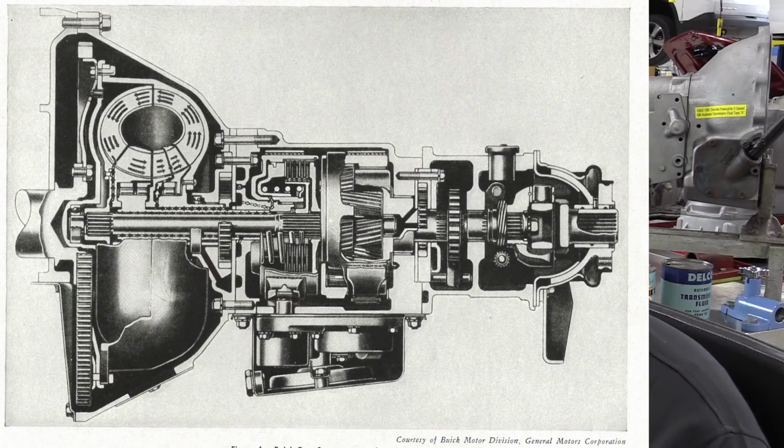It does not increase the power of the engine, but it increases the power delivered from the engine to the input shaft. Well, this torque converter has 3 stators in it and has a torque multiplication factor of almost 2.6 to 1. So you could take engine torque and multiply it by 2.6 under heavy acceleration conditions and make it feel like it had more than just 2 gears in the automatic transmission as far as how quickly it would accelerate. The problem with this unique torque converter design, though, is that it created even more heat. And that additional heat required a better fluid.